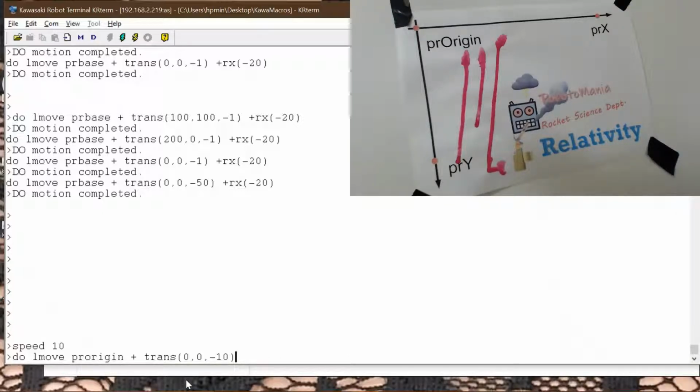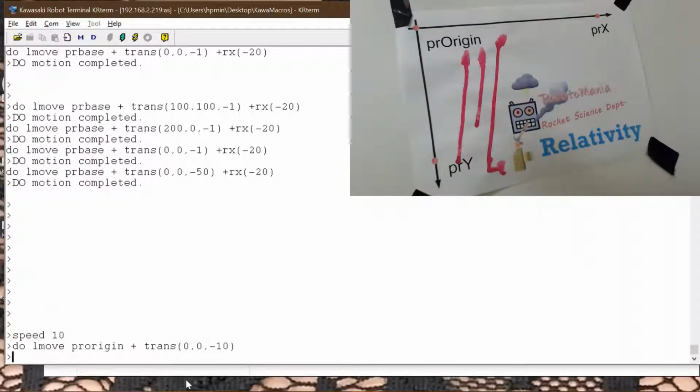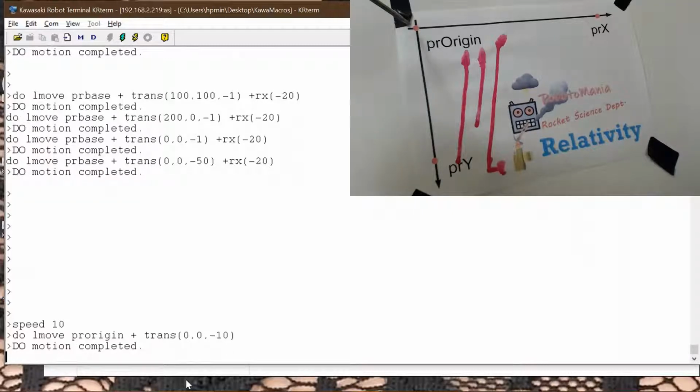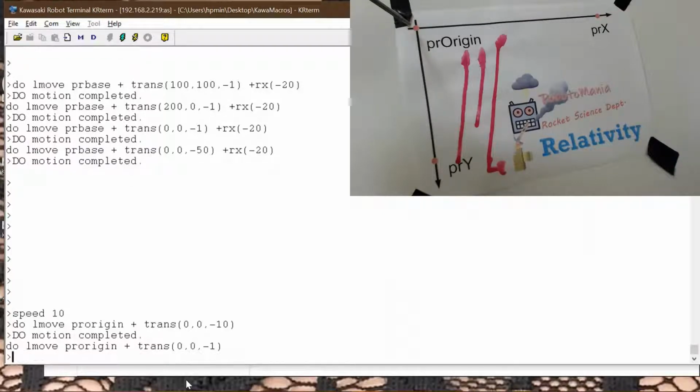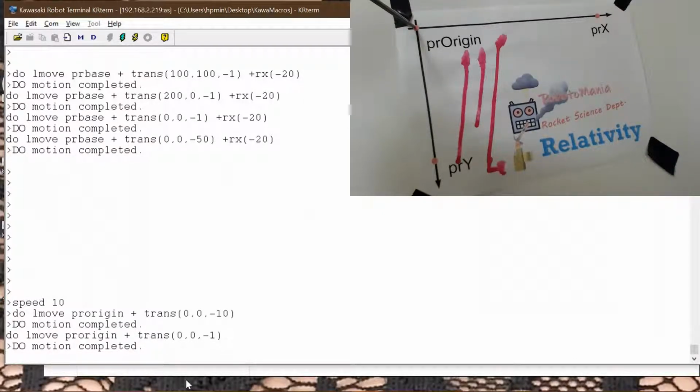And okay, maybe I'll make another video about the tool reference frame and how to use it and what it really is. But for the moment, let's assume that this is a known topic, so we just do a little refresher. So let's see what gives. I'll try to do the start. And obviously my robot comes a little bit around. And the visibility may not be exactly as expected from the camera point of view, but this is just a check. So let's go and land completely. I always like to land in small steps. So I give 1 millimeter, which is already a good deal.